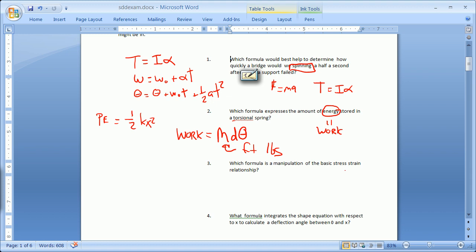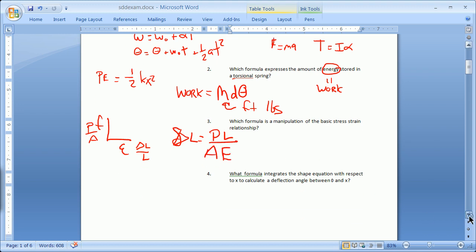The best stress-strain relationship, it's best to do this, stress and strain, and that is P over A, and that is delta L over L. This is deflection, or delta L. I guess delta L equals P, the force, times the length divided by the area times the modulus of elasticity. Please don't just remember this. Please remember the stress-strain of steel, the stress-strain of concrete, the stress-strains of soil, it being the stiffness and having units of psi, because this is unitless.